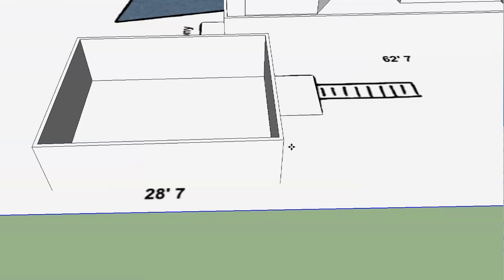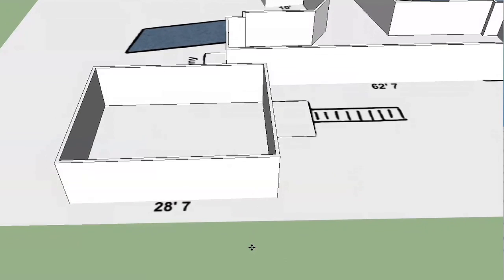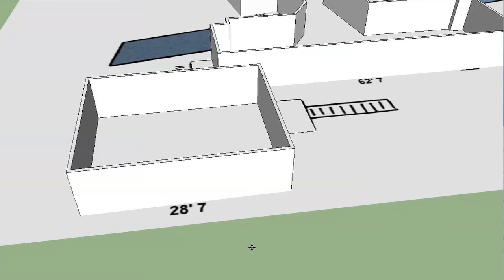Now, if you recall correctly, the floor that we modeled was 8 inches thick. So let's go ahead and type in 8. There we go. Now, at first, you might think that didn't do anything because we still can't see it. Well, that's because now the floor plan is in the same location as the top of our floor on the inside of our house, but we've still got the actual floor there. So we need to remove the floor just temporarily.